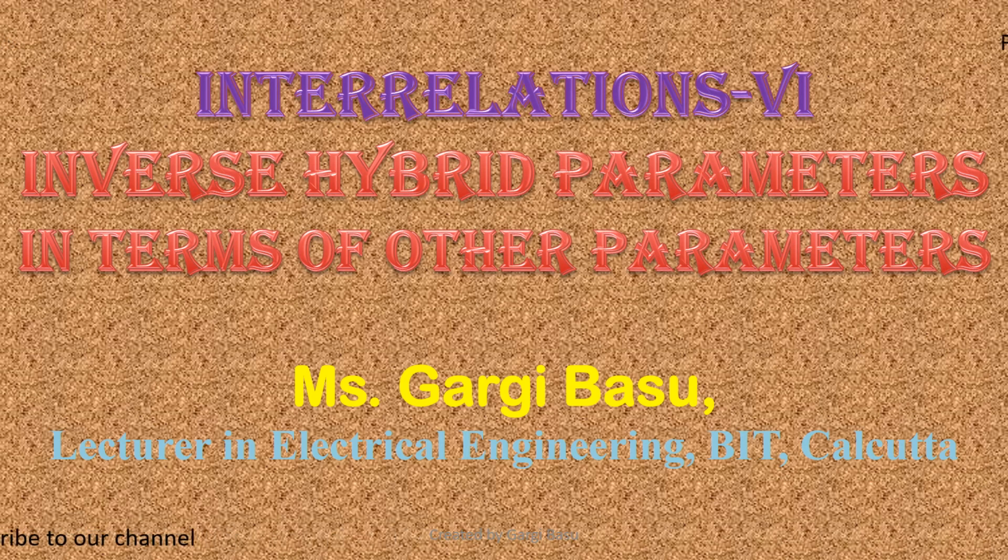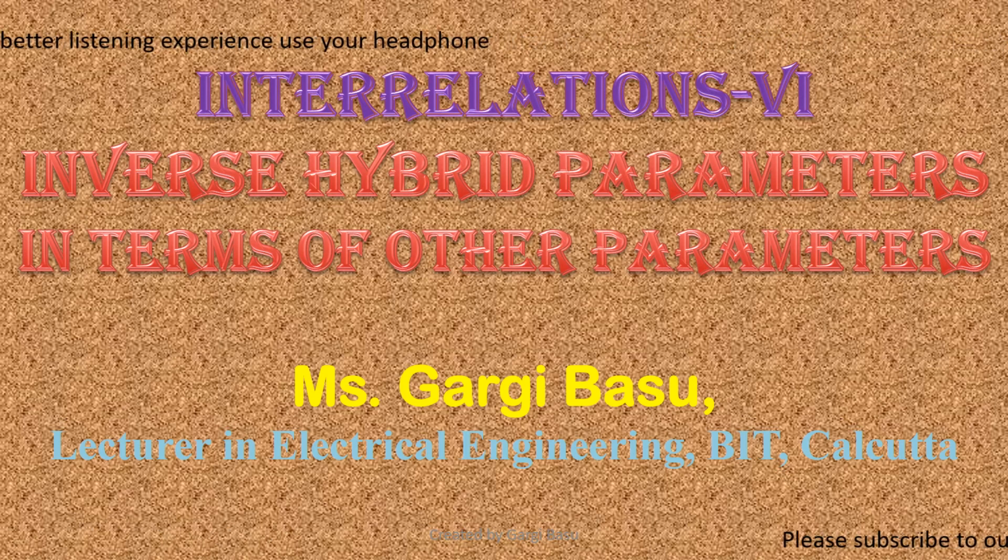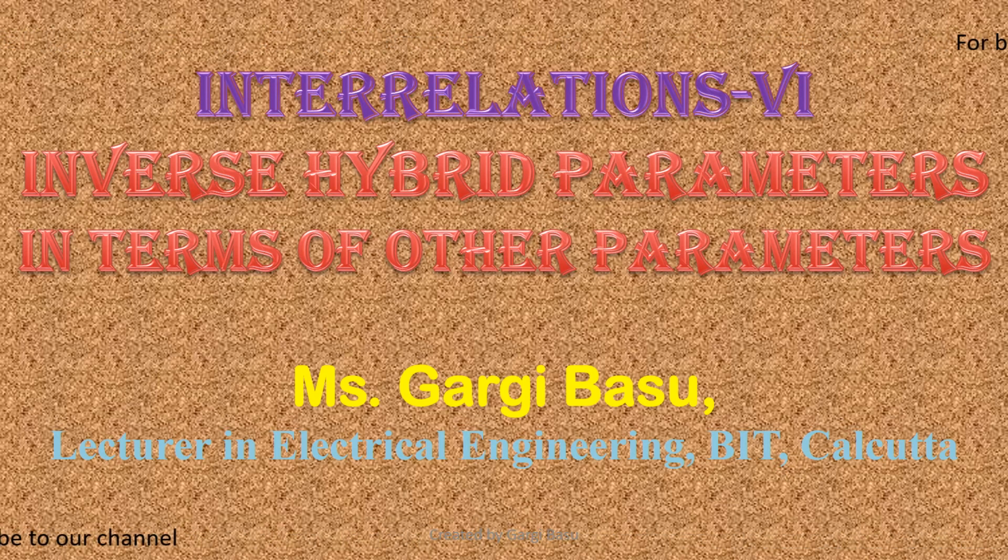We have learned that an electrical network is called a two-port network when it comprises one input port and one output port. We can describe a two-port network in 6 manners. Each method uses a set of 4 parameters. As all the sets of parameters describe the same two-port network, there exist definite relationships between them. Today we shall establish interrelationships between inverse hybrid parameters and the other sets of parameters.